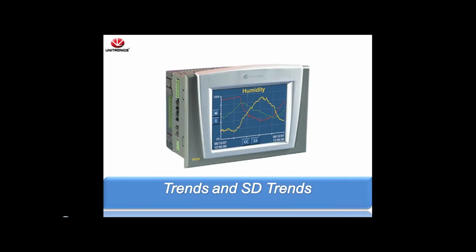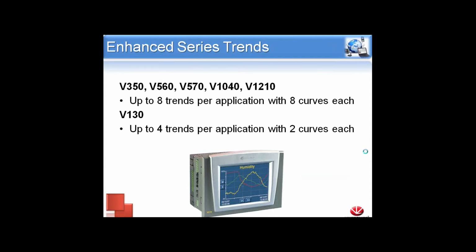Today we'll be talking about trends on our enhanced series controllers as well as the SD trends. Like I said, the enhanced series controllers include the V350, the V560, V570, V1040, and the V1210. On these controllers you can have 8 separate trend graphs per application. On each graph, we can show 8 different curves at the same time. On the V130, we can have 4 different trends per application with 2 curves on each.